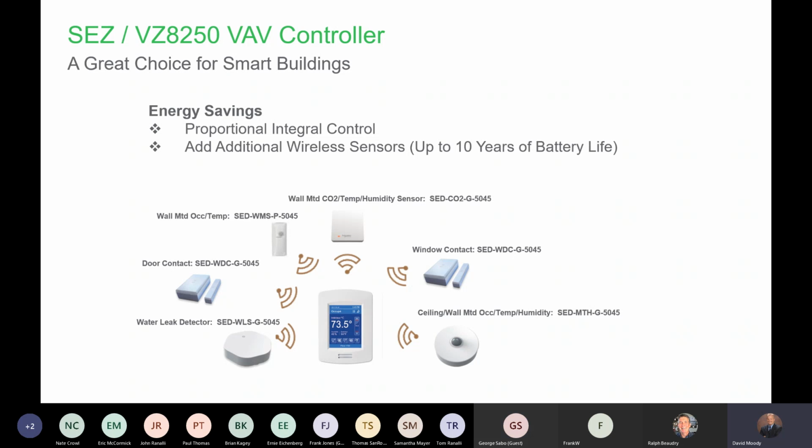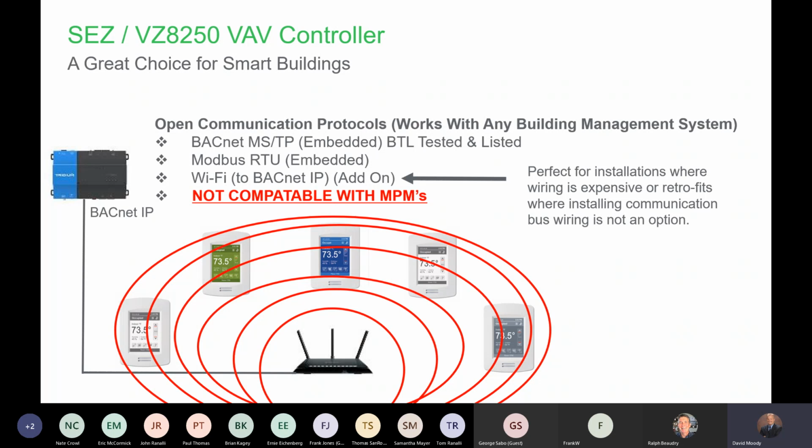No, so the wall device, the room controller in the middle, has to have a ZigBee radio embedded on it to do that. Okay, so is it ZigBee or Wi-Fi? Very good question. The ZigBee, which is what we're looking at right here, is for field devices. Wi-Fi is your network trunk back to your supervisory type system.